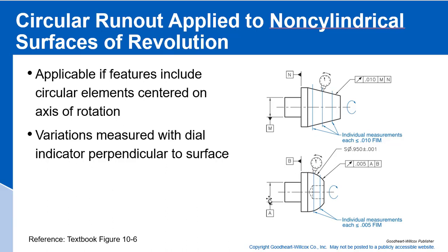And here we have another feature. It's more like a spherical feature, and we fix the dial indicator at a certain position, and we spin the part around, and we evaluate these individual surface elements for runout.